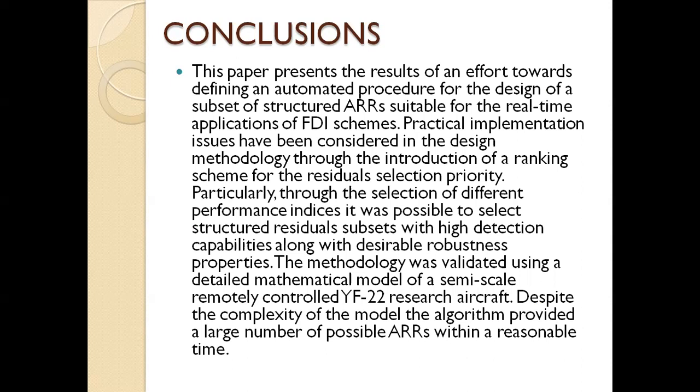Coming to the conclusions, the paper represents the results of an effort towards defining an automated procedure for the design of subsets of structured ARRs suitable for real-time application of FDI schemes. Practical implementation should be considered in the design methodology through the introduction of ranking for residual selection priority, particularly the selection of different performance indices, so that it was possible to select structural residual subsets with high detection capabilities along with desirable robustness properties. The methodology was validated using a detailed mathematical model of the semi-scale remotely controlled YF-22 research aircraft.